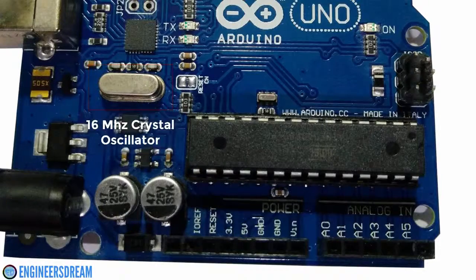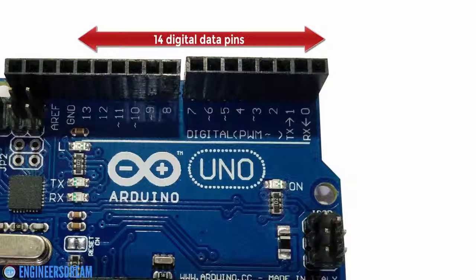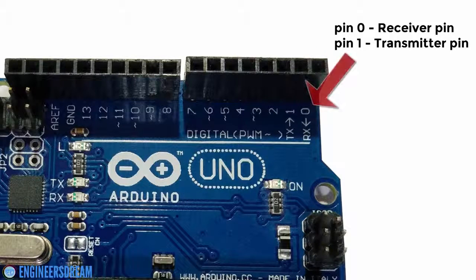And as I told you earlier, the Arduino board consists of 14 digital pins which are labeled from 0 to 13. If we look at pin number 0 and 1, over here RX and TX is written, which stands for receiver and transmitter. So we can basically use pin number 0 and 1 for serial communication, that is for communication between a Bluetooth, GSM or even your computer.